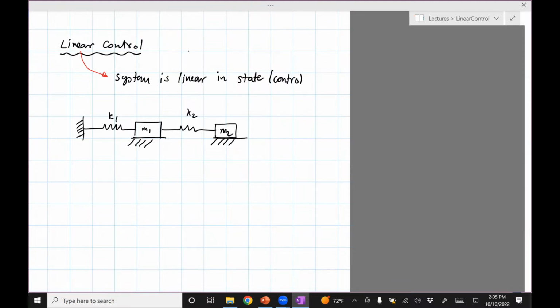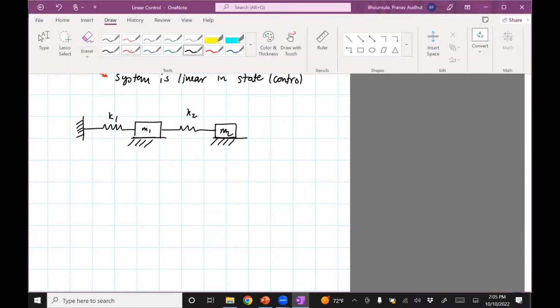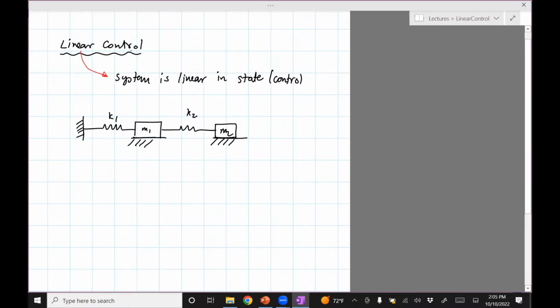The left side there's a wall. I'm going to indicate a control. In this case, the control is going to be a force. Let's say that this control is U2 on mass M2. And then there's another control, U1, which pushes M1 to the left and M2 to the right when it is actuated. So in this case, U1, U2 would come from linear motors, things which move in straight lines as opposed to moving in circles.